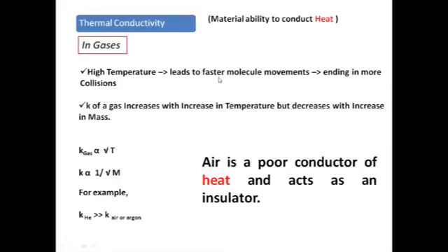So with increase in temperature, molecules move faster, resulting in more collisions, and hence for a gas, thermal conductivity increases with increase in temperature, but decreases with increase in mass. So we can say thermal conductivity of a gas is directly proportional to the square root of absolute temperature and inversely proportional to the square root of molar mass.